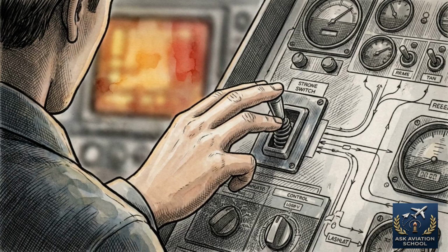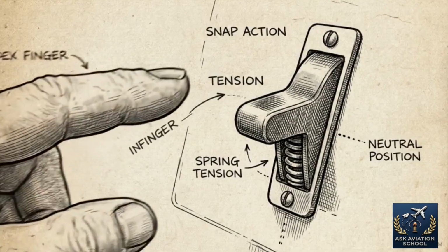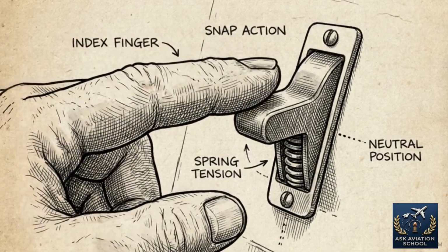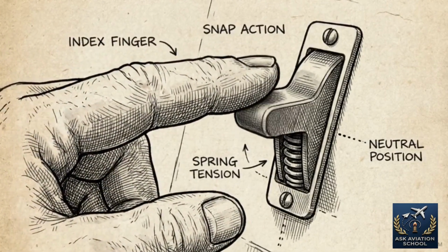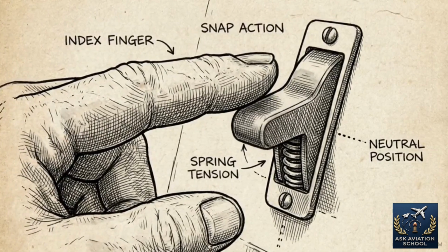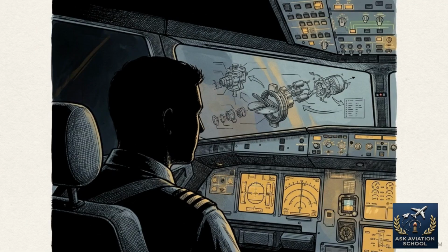There is a 5-second latency in the ECAM display because of the backup pressure sensor's resolution. To target a specific vertical speed, the crew must apply very short inputs to the toggle switch and wait for the system to catch up. Selecting manual mode moves the responsibility for the airframe's pressure limits directly to the flight crew.